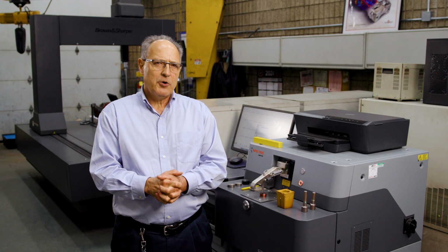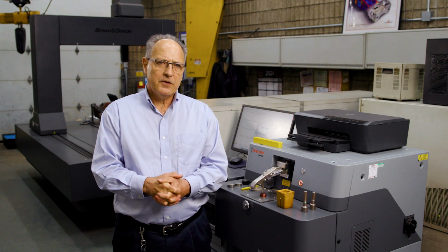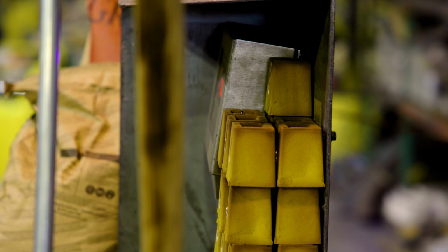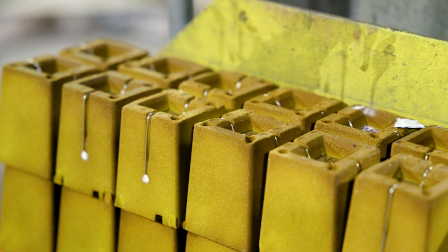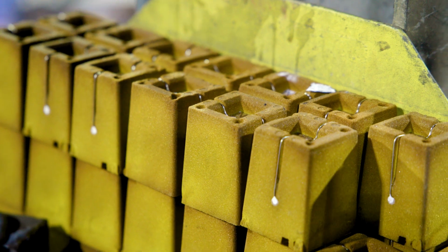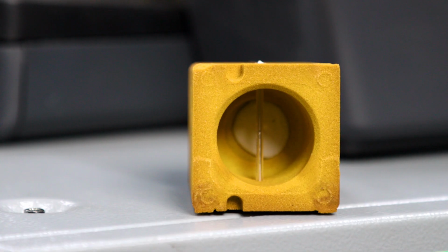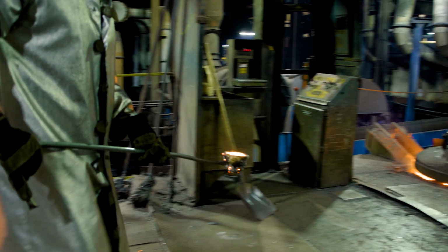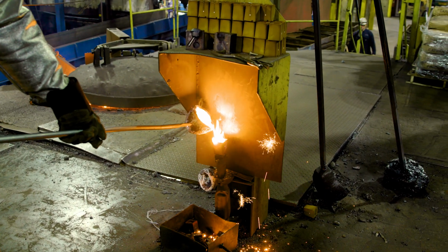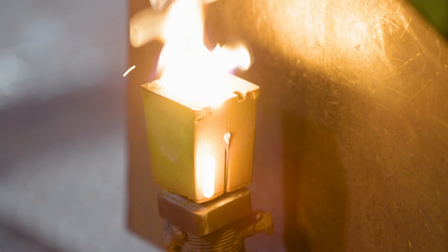Okay, now we're going to talk about process control, starting in the melt department. Again, in cast iron, we analyze 22 elements. So the melt guys have a device called a thermal analysis, which uses this cup. It's a sand cup with a thermocouple. You can see two different wires. They are welded in the middle. So when you pour the liquid iron inside of that cup, this thermocouple is going to check the temperature.